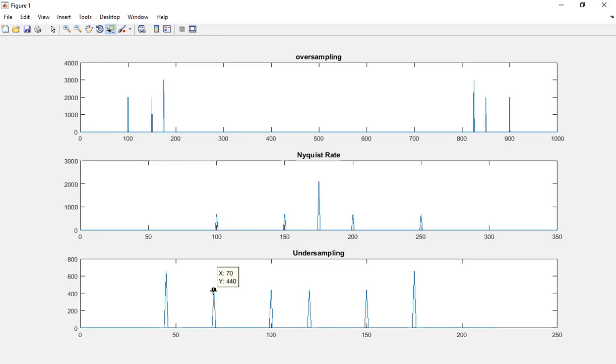This is what is going to happen when you do not want to spend on memory, on bandwidth, or maybe on power, then you end up getting these fellows here. The problem is called aliasing. That's why oversampling is good, but it's going to cost you bandwidth, speed, and memory. Nyquist rate is the boundary. Undersampling is a disaster. So that's about the sampling theorem.